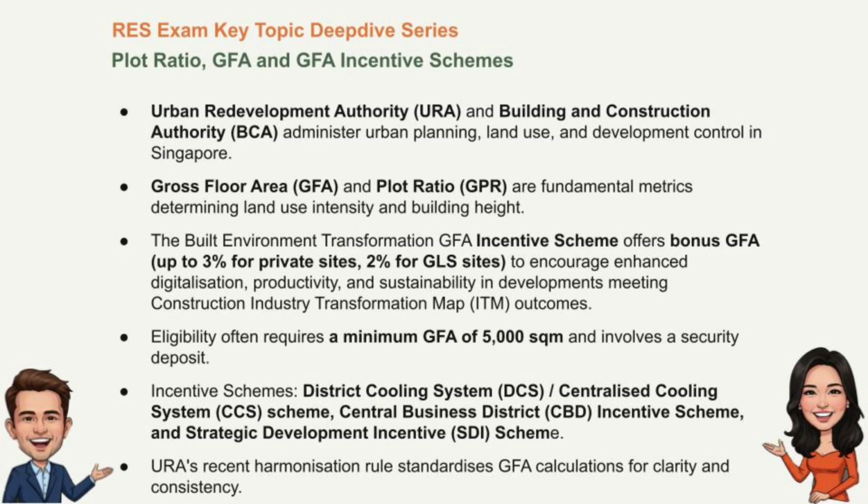And the third one, sustainability. Sustainability sets a very high bar. Developers must achieve the Green Mark Platinum Super Low Energy, SLE, certification. Platinum SLE, that's tough. It is. And specifically, they need exemplary performance under the maintainability section of the latest Green Mark framework, GM 2021, meaning scoring at least 10 out of 15 points there. So it's not just about building an energy-efficient building initially, but one that's designed to be easy and efficient to maintain throughout its life, minimizing long-term environmental impact. Wow, that's a serious commitment across the board.